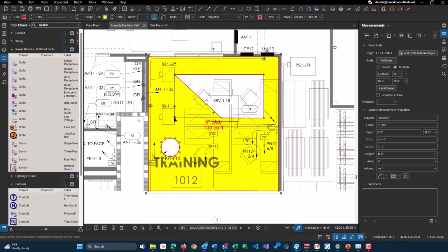A rectangle now, I should say. And again, all of the numbers and takeoffs within Bluebeam dynamically update as you make changes. It is quite simple to change out a drawing and keep your markups, especially whenever there is a bulletin, and you can go through there.